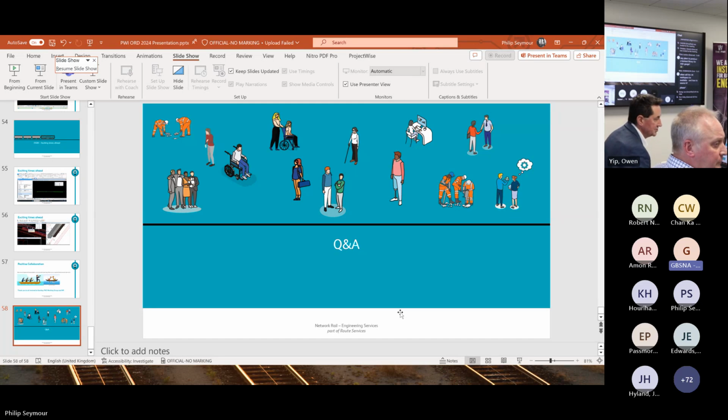If you're in ProjectWise, of course, you can lock down those files for access. Could even lock it in MicroStation if you wanted to, but federation is really the key. So I could do the up and the down main in one file, maybe the siding and the yard in another file. I place a turnout, I reference in the mainline, the turnout's plate. It understands that rule. So if that turnout radius changes from 5,000 to 20,000 or something, it understands that. So it's not just dump everything in one file.